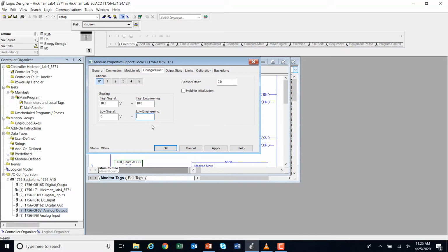Let's say 32 degrees was freezing and 212 degrees was boiling. Okay, so if this card took in 0 volts, then it would know that it was 32 degrees. If it took in 1 volt, it's going to be more than 32. You can do the ratio here. It's going to be 18 degrees more, and we'll do that in a minute. It'd be 50 degrees, okay?